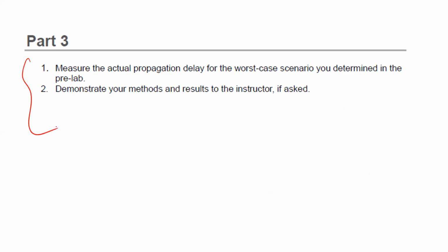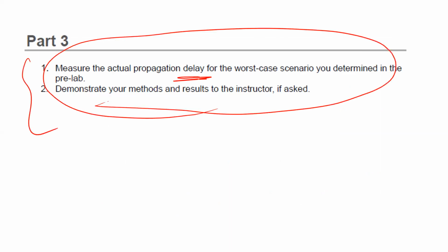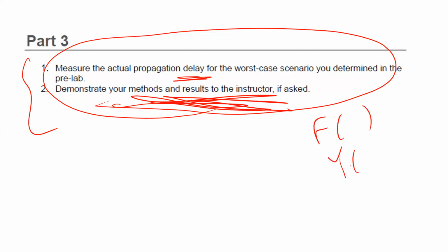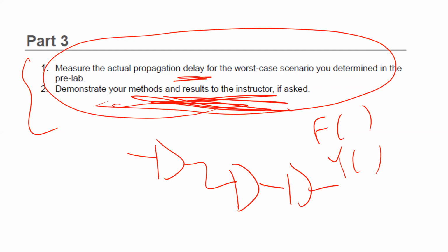Finally, here I'm asking you to measure the propagation delay. Based on what you determined in the pre-lab, determine your method and show the results to the instructor if asked. I didn't tell you for which one, so I would suggest doing it for f and y because we have 2 functions. As I told you before, for the worst case propagation delay, you can fix all inputs except 1.